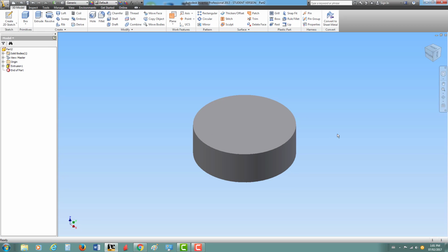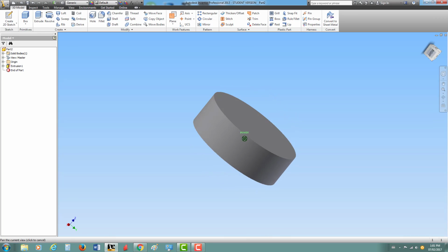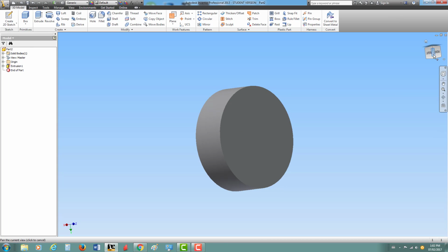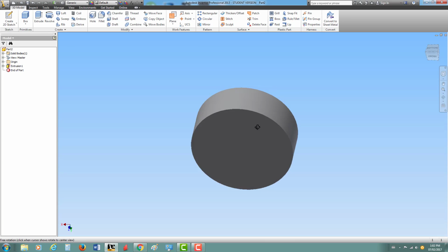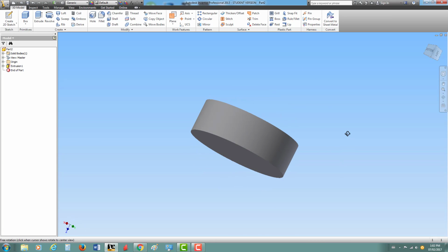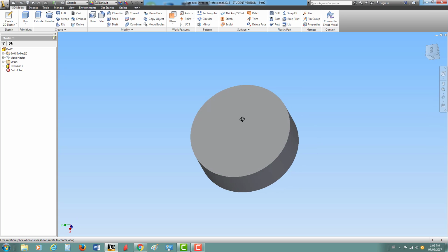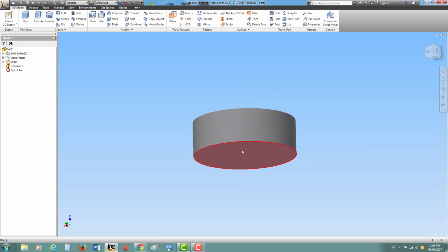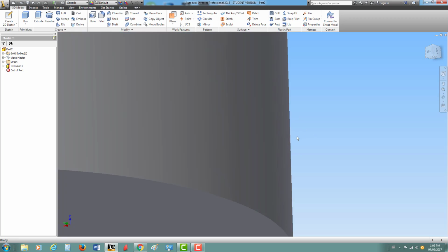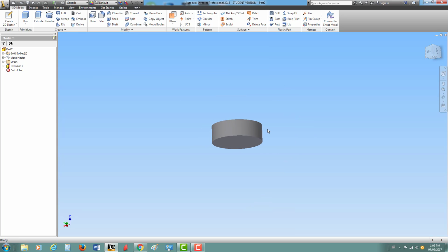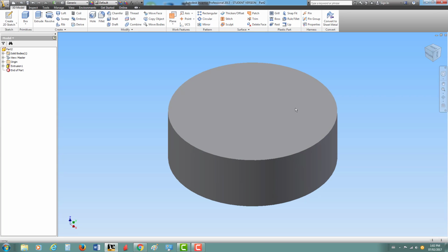The other thing you can do is if you want to rotate, now I can click on the block and rotate it around just by clicking and holding on the little cube in the top right corner. Or I can press and hold shift while middle mouse clicking, and I can do the same thing, but without having to move all the way over wherever I am. Okay, so just a couple things. So let's quickly recap. Zoom in, zoom out, pan, shift, middle click to rotate. Okay, I'm going to click on the home button, so I'm back to where I was originally.